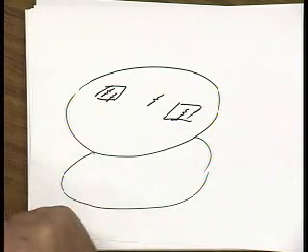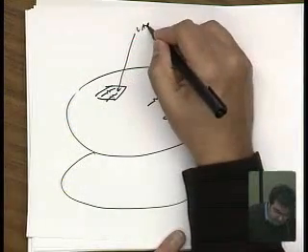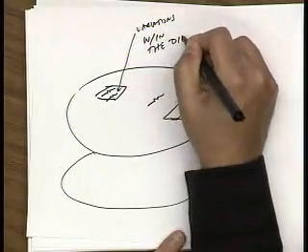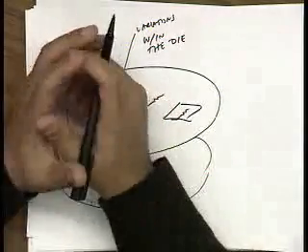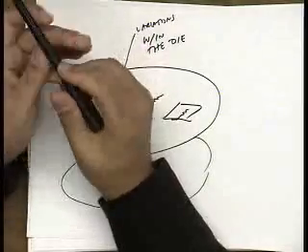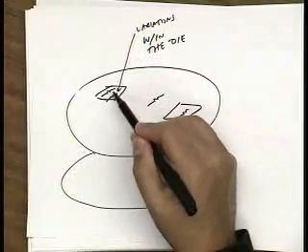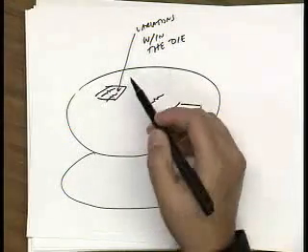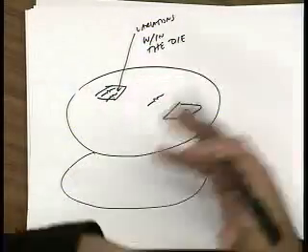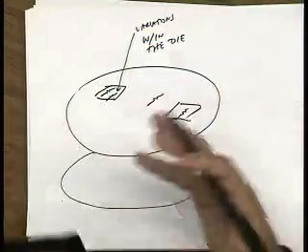If you design your circuits right, what you should really be concerned about is variations within the die. In other words, for structures that are physically close together. If you put structures physically close together, variation will be very small. Okay? And so even though you don't know the absolute value of this resistor, it's not going to be 100 ohms, it's going to be maybe 110 ohms, the guy right next to it is not going to vary just as much. It's going to vary probably by 2-3%, depending on how close you are.